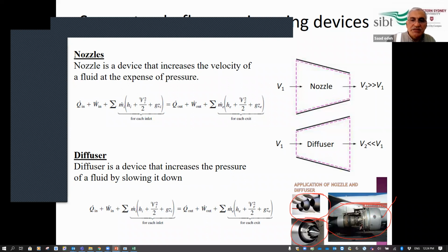So that's why we call it a fluid. But sometimes we use a diffuser, let's say, for liquids. For example, we have a pump and we need high pressure from the pump. We use a diffuser. So we are pumping water under high pressure. We need a diffuser at the end, not a nozzle. So this is the difference. But in general, we say fluid because we may use this diffuser for a liquid or a gas, no matter. Okay.